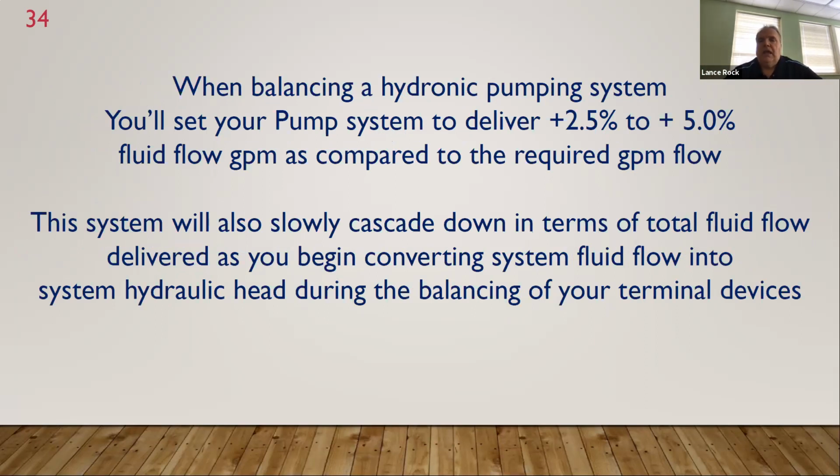A hydronic pumping system is a little more exact, and there's not the duct leakage. When you're balancing with airflow, you have duct leakage. You clearly shouldn't and probably don't have hydronic pipes leaking, because you would see them in the ceiling. No one's identifying the leakage in duct systems. So that +5 to 10%, part of that is losing airflow into the ceiling because the ducts were not sealed properly.